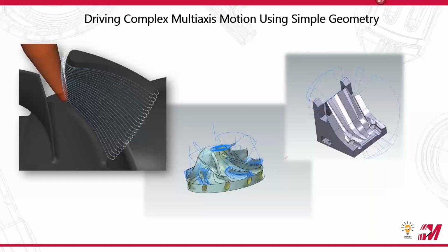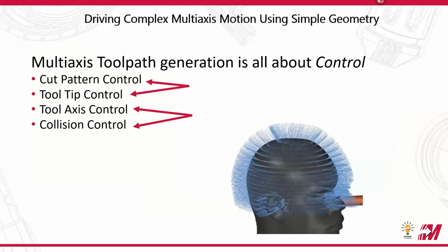And to drive the tool motion for this, we need to understand how to program this in a manner that we will be able to picture and edit in the future. When you look at a multi-axis path or a surface that you're going to be pathing, you have this picture in your mind of what you envision the tool motion to be as it crosses that surface. So how do you translate that from your mind to a finished tool path that you're posting and running on the machine? There are 2 core concepts that enable that for multi-axis machining.